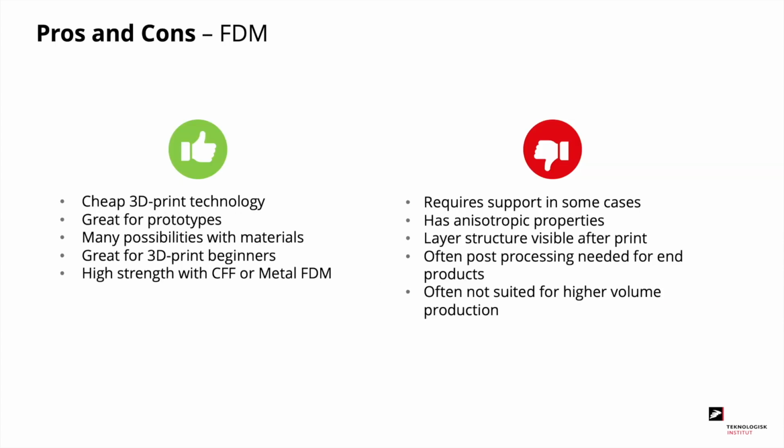So to sum up the pros and cons for FDM printing, on the pro side, we have a cheap 3D printer that is great for prototypes, and it has a wide range of materials to choose from. It is great for beginners, and if you want even stronger parts, you can use CFF or metal FDM printing.